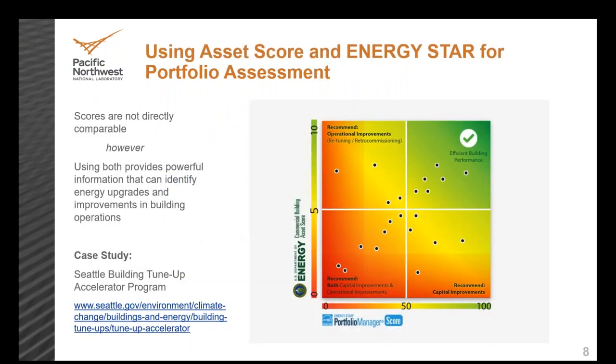I do want to point out that the scores of the two tools are not directly comparable. Once again, Asset Score reflects modeled energy use under standard operating conditions, while Portfolio Manager scores reflect measured energy use under actual operating conditions. However, using both tools gives users powerful information that can inform both energy upgrades and improvements in building operations.